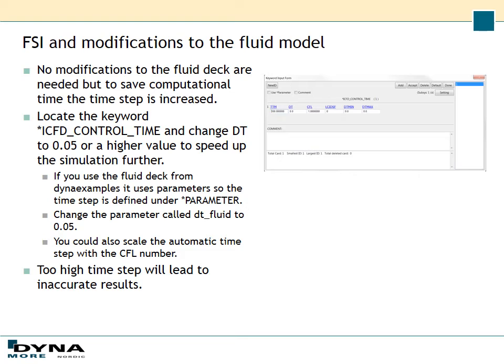No modifications to the fluid deck are needed, but to save computational time we will increase the time step. So locate the keyword ICFD control time and then change the DT parameter to 0.05.